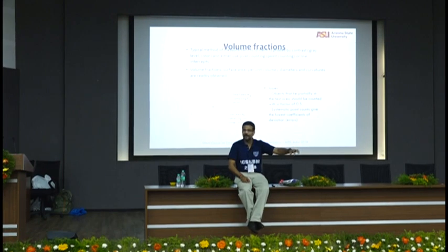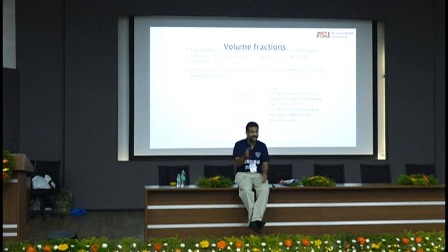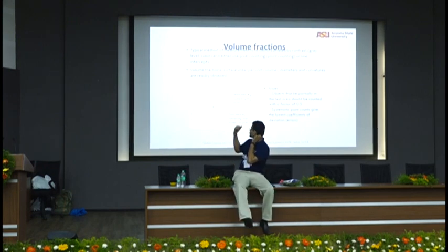And if the crosshairs fall on the boundary, I make a judgment on whether I call it a pore, an aggregate, or a paste. The first few times it will be correct, and after that you get fatigued, and whichever finger is close, you press that. Right? It will take 3 or 4 hours to do one sample. It used to be very tedious. To minimize error, we have at least 2 people do it and compare results so they are correct. Very tedious process. That was a counting process, which is very similar to this.